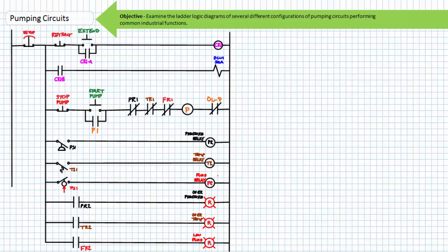We had a brief discussion of overloads common with each other, in series with each other, and in a cascading arrangement with each other. Finally, we examined 2 types of diagnostic circuits that both serve to turn off the pump and turn on an appropriate warning light, one utilizing mechanically interlocked switches, and the other utilizing control relays and associated contacts.